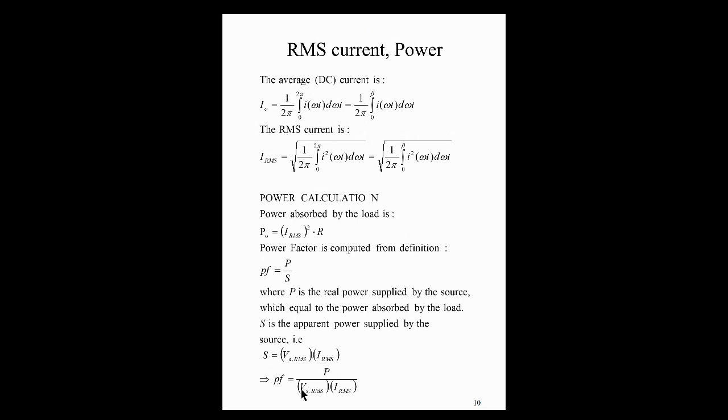So we can substitute this formula, where we have true power or real power divided by the product of the input voltage and current, with their RMS values.